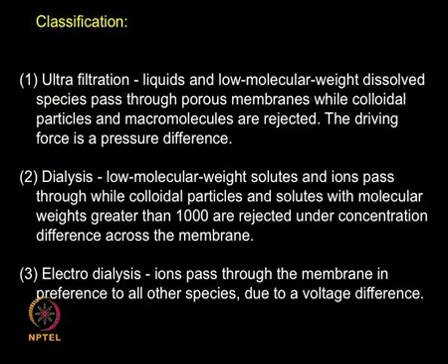Ultrafiltration, so where do you use ultrafiltration? We can use it for liquids and low molecular weight dissolved species, colloid particles, macromolecules, they can be rejected or captured. So here the driving force is the pressure, so it is almost like a normal filter. So there are holes, molecules or salt which are larger than the holes get rejected, only the liquid goes through.